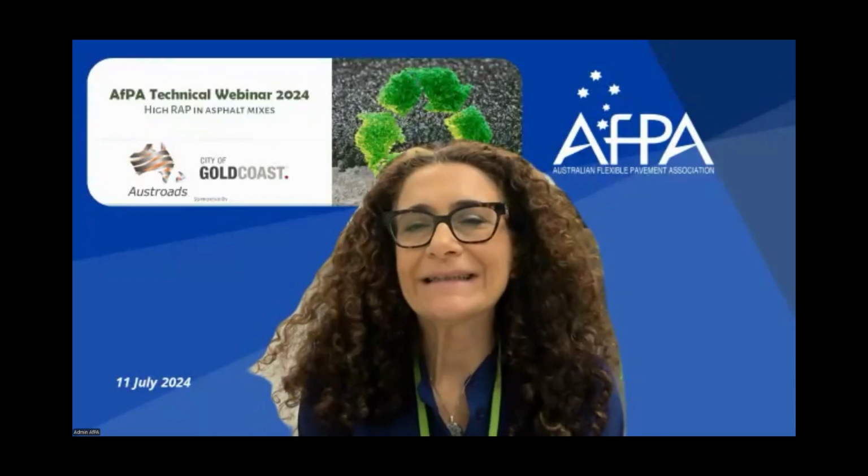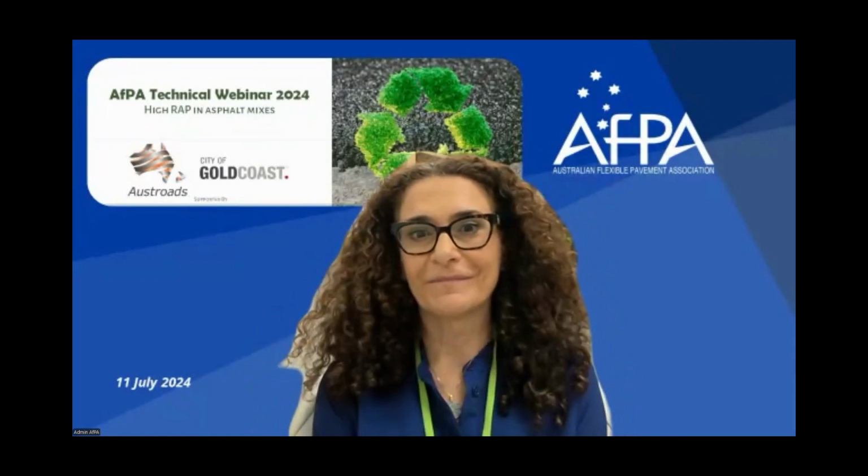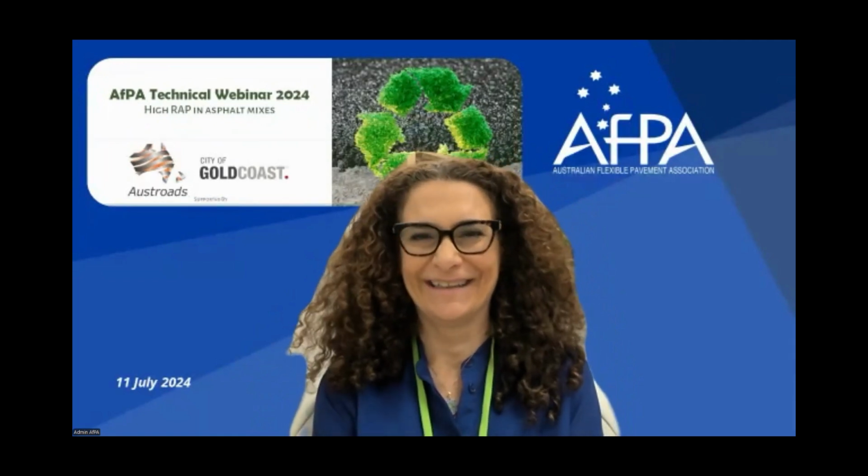Thank you. I have a comment from Steve. Steve talked about cold process. What about a DG with C600 and 25% RAP, bumped down to C320, but made as warm mix asphalt at 135 degrees? Should we use a rejuvenator to get the RAP mobile considering lower temperature of virgin aggregates? Is this question clear? Yeah.